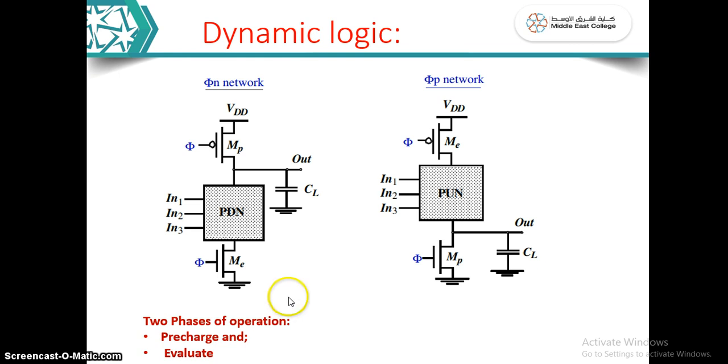The operation of all dynamic logic gates depends on a temporary storage of charge in the parasitic node capacitance instead of relying on a steady state circuit behavior. So in this case, we need to periodically update the internal node voltage, since stored charge in a capacitor cannot be retained indefinitely. So, dynamic logic gates require periodic clock signals to control the charge refresh.